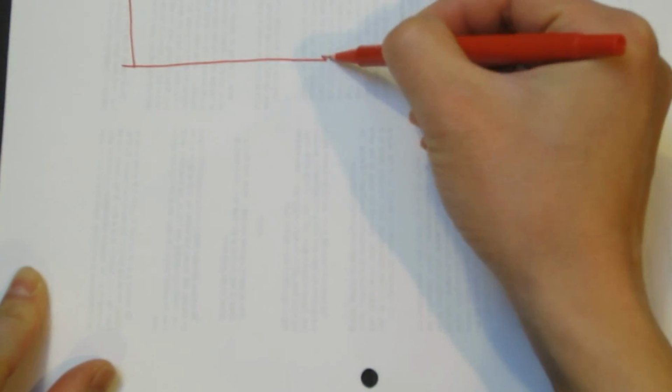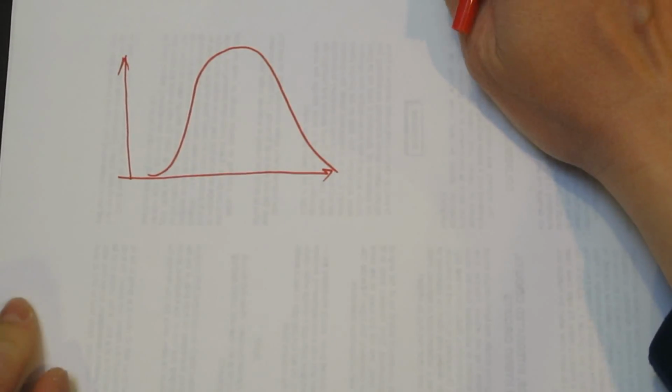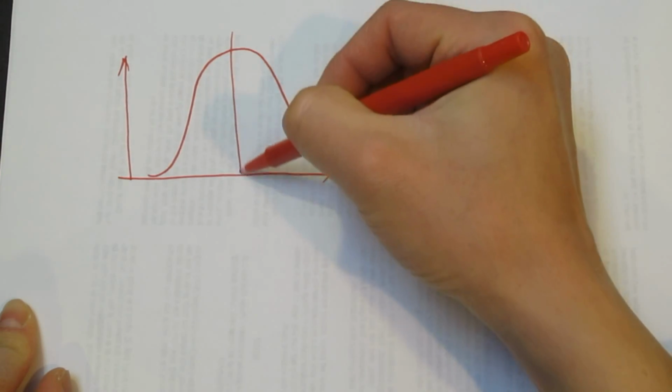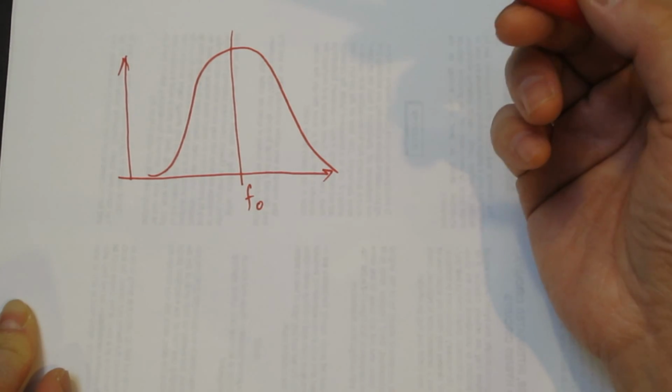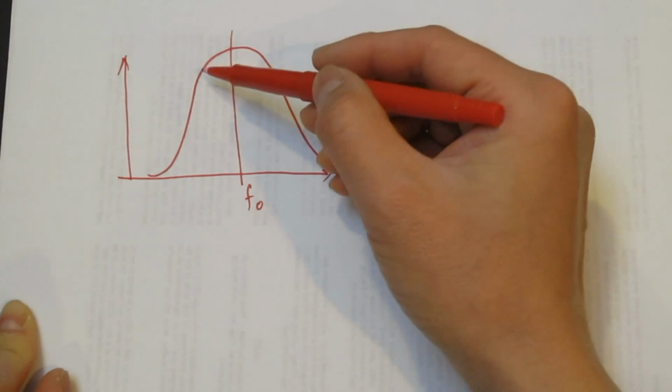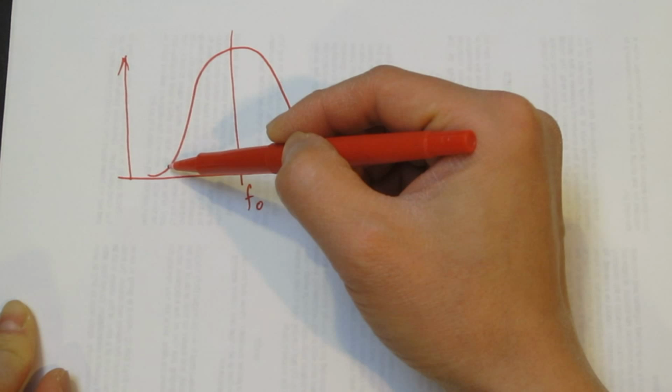Now let's take a look at how this is done in the spectrum analyzer. Again, we have this filter bandwidth set by our bandpass filter, and the filter has the typical curve of a Gaussian. That's how most filters' characteristic curves look. Let me move this down a little bit. This one has a center frequency of f0. Our signal passes through, and remember the characteristics of this slope. If our signal sits at this frequency, the output amplitude is going to be small.